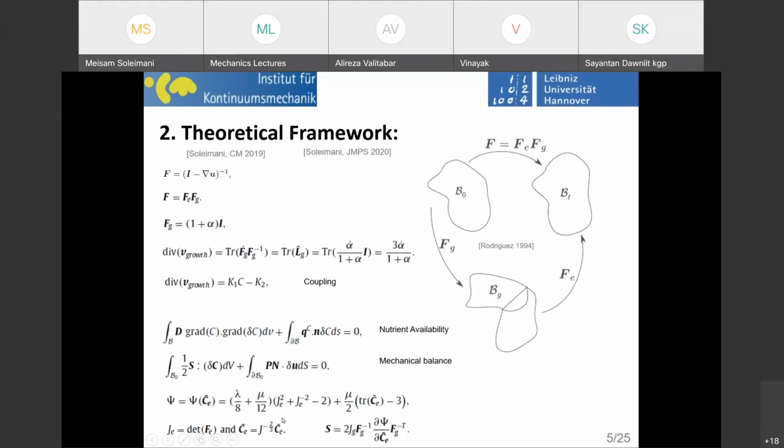But as you mentioned, there are two possibilities if we are talking about growth phenomena: we can define the free energy per unit mass or per unit volume. For sure, if you want, you can convert them by dividing by rho. If something is per unit volume, multiplying it by rho, that is meter cubed divided by kilogram, converts it into joule per kilogram. But the problem is that if you define it like this, then you need to also treat density, rho, as a variable.